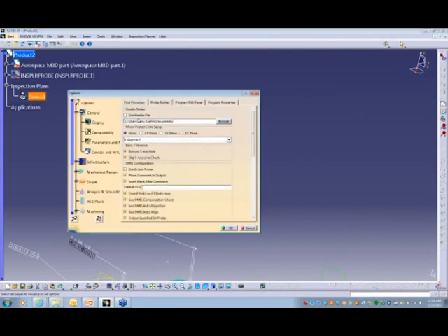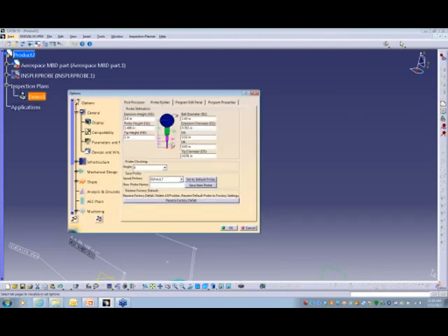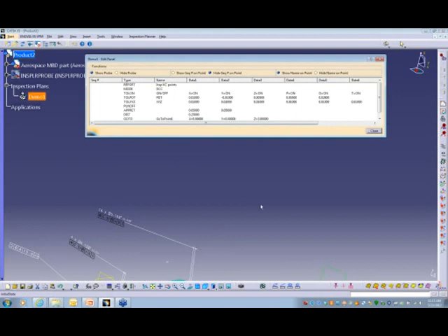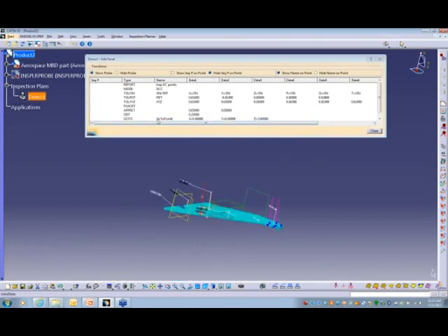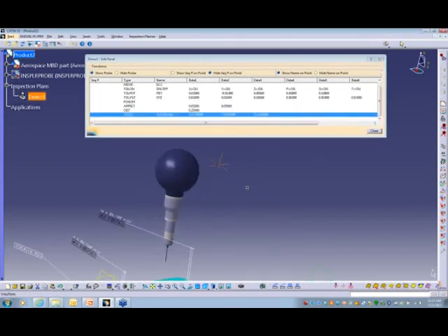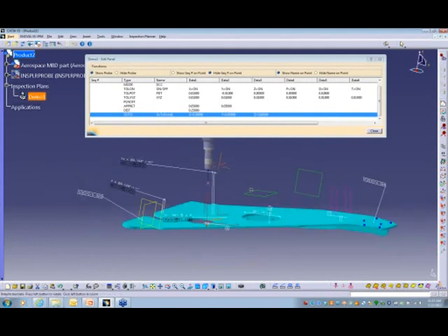We have post-processor settings for doing mirroring and some custom DMIS type stuff. And we have a probe builder, so you can build the probe that you're using and save it off in a library. So we'll go back to where we were at. That probe was just kind of a standard Renishaw probe.